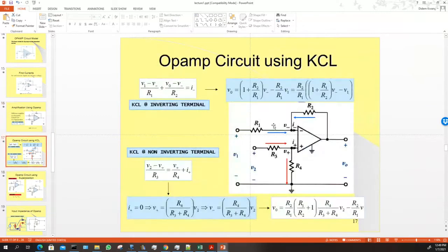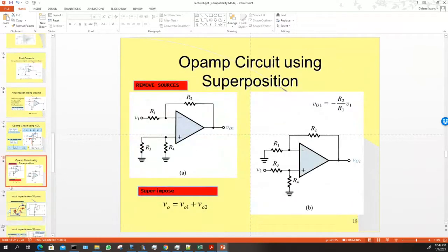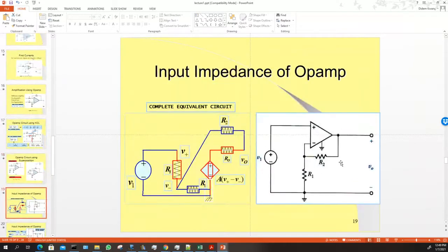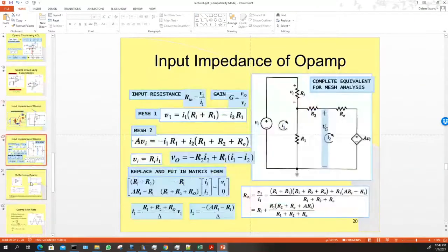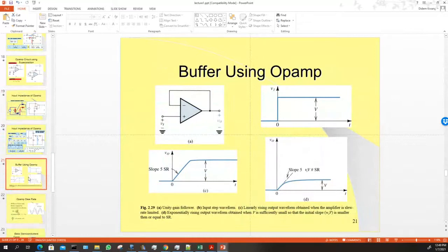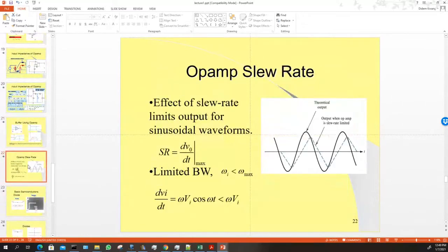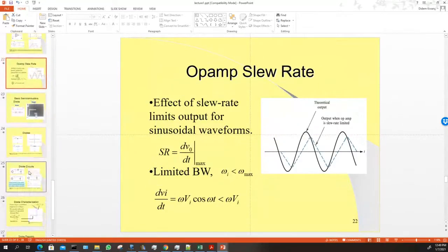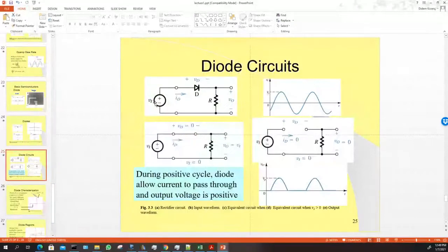But if you actually go into, oh, well, I minus is not exactly 0 and I plus is not exactly 0, and maybe we should model those. And maybe we should look at the output as well. This is supposed to be infinite, I'm sorry, 0 resistance at the output, but maybe that's not exactly true. So you go into a deeper and more detailed model of the system, then you can do more analysis. If you need that kind of performance from the system, you're going to have to model it in more detail.